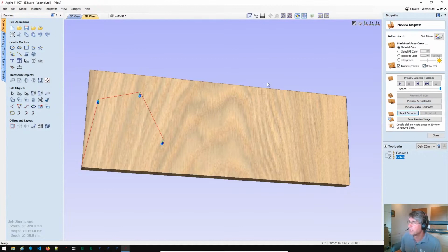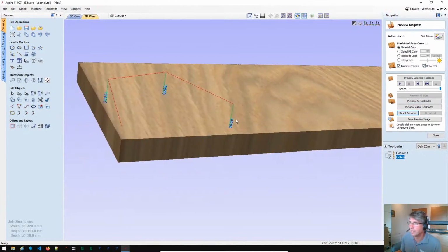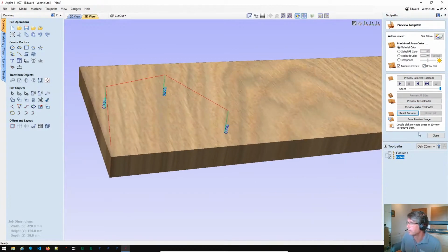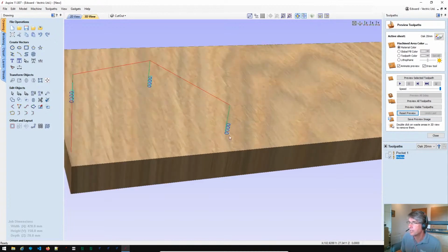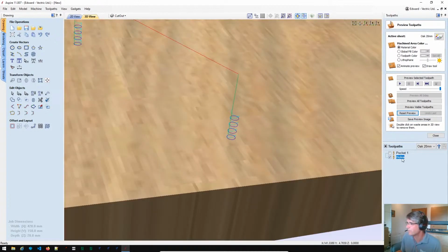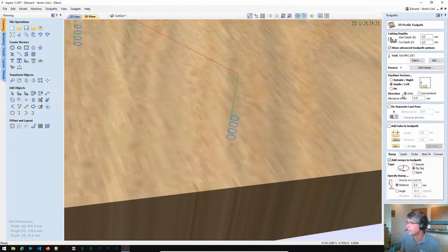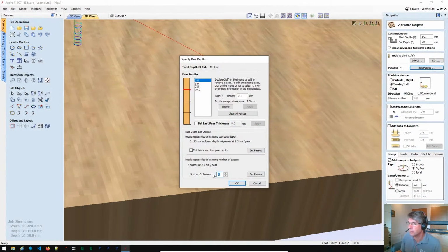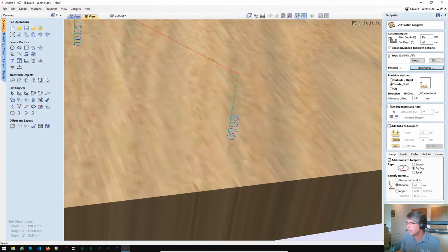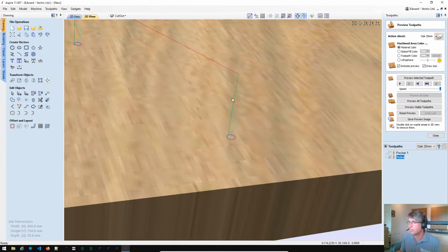Right, so when I'm using profiling to do drilling, or hole cutting like that, I need it to come inside. Now you can see I'm back to my 4 passes, so we'll drop that down. We don't need it to do 4 passes and retracts. So I'm going to risk just getting in there. Set the passes at 1. Okay, calculate. Let's make sure that looks right. Right, that does look right.